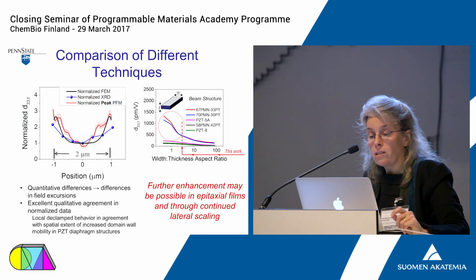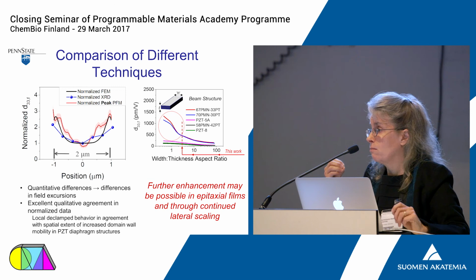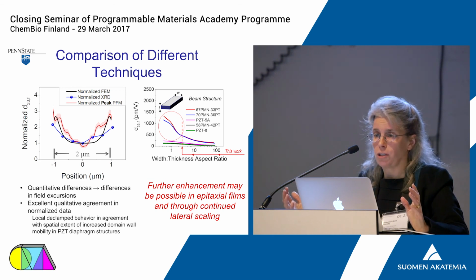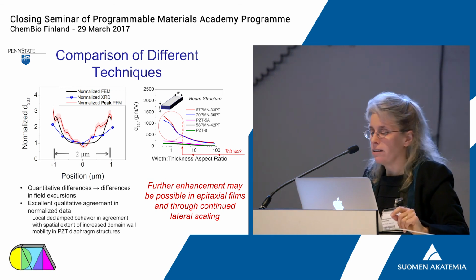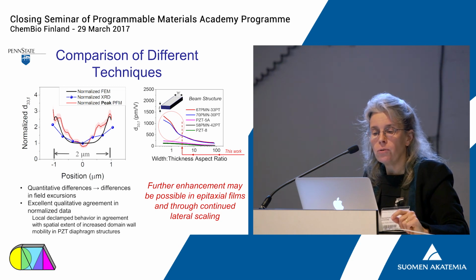If we estimate, so that's where we actually made our experimental results. We physically know how to grow features down to about this size, and so it looks like we actually can achieve the piezoelectric coefficient in real materials, even those made by chemical solution deposition, to actually run the piezoelectronic transistor. These data show comparisons of the X-ray measurements in blue with atomic force microscope measurements in red and the finite element model in black, and the 3 data sets overlay fairly nicely.